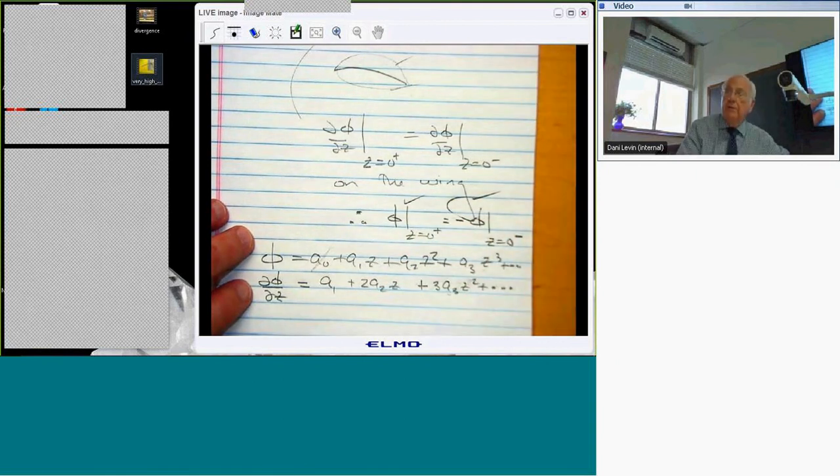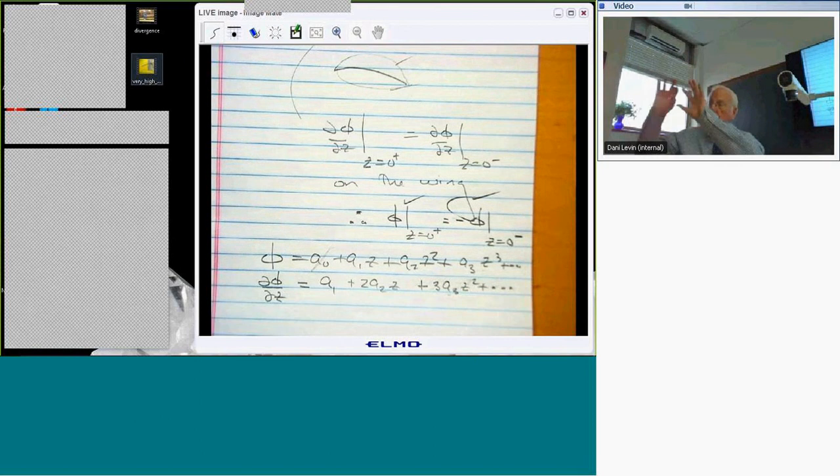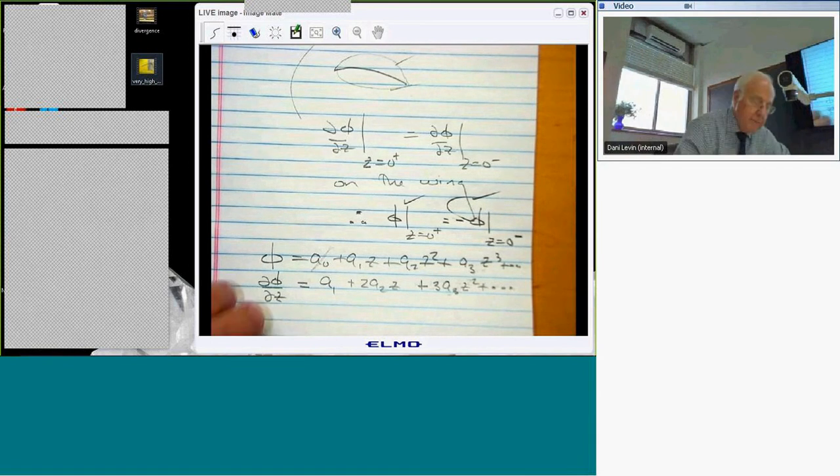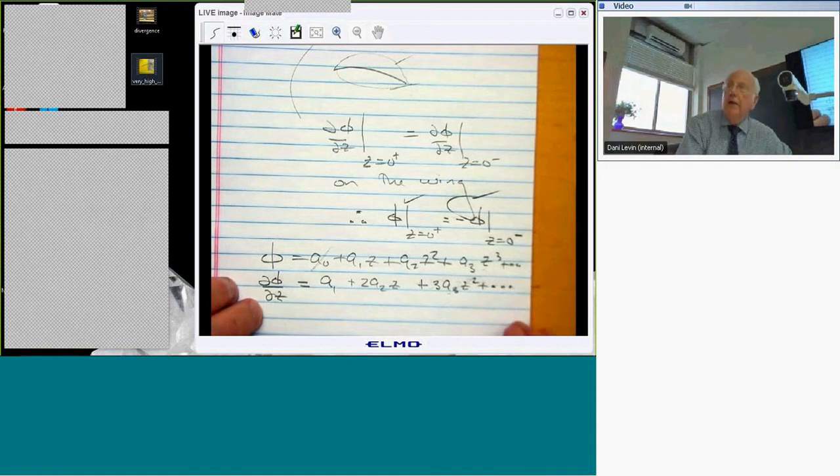Again, appealing to the fact that when I go to the trailing edge or leading edge, there must be continuity between what's happening on the wing and what's happening off the wing. Okay. Yes. If it's true at the boundary of the trailing edge, where the air meets the wing, why does it still need to be true off the wing? If phi is 0 at the boundary, what says it's still 0 a meter downstream?